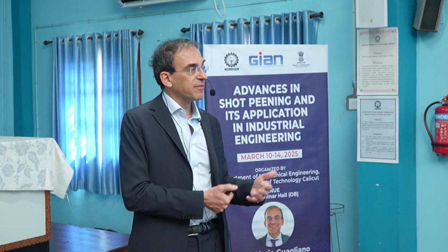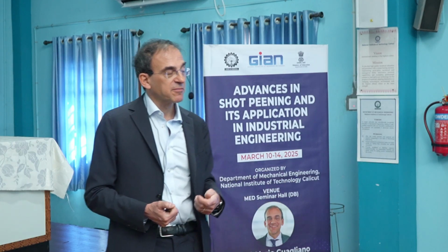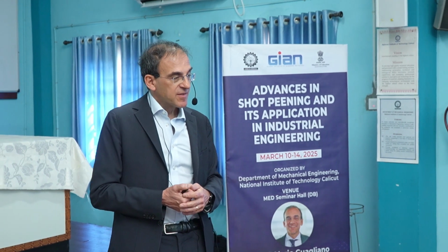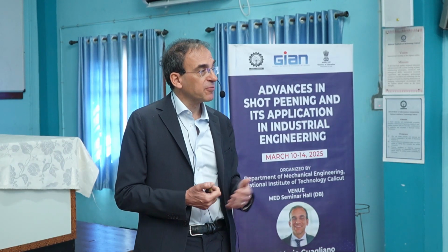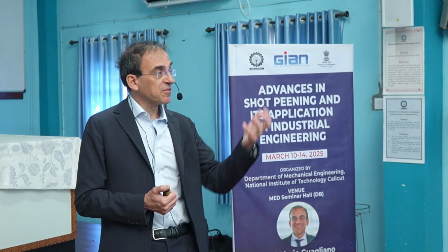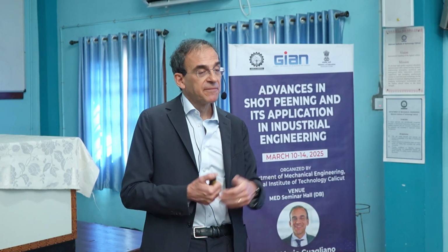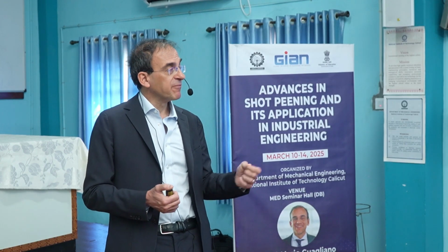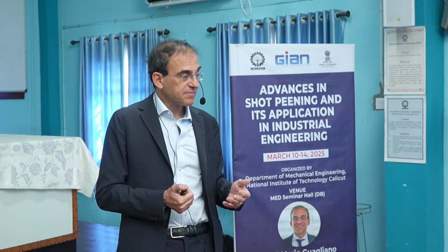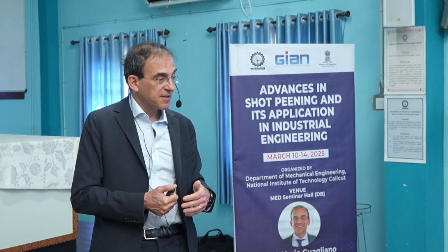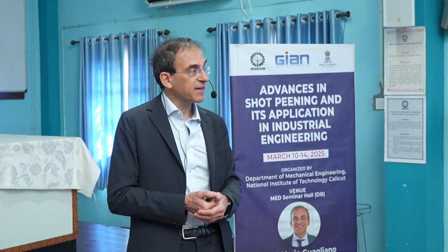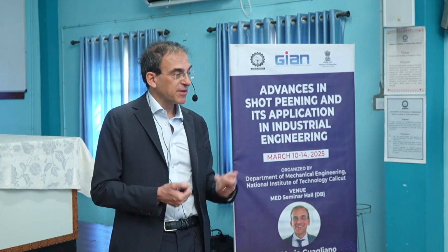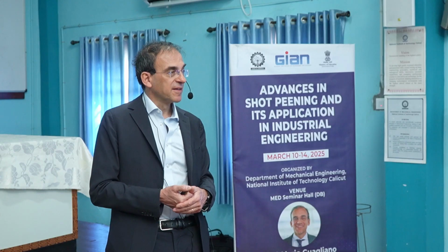Initially, in terms of macro residual stresses, and then also in terms of hardening, we will see, and in terms of surface finishing, surface roughness. So initially with the finite element model, with simplified approaches, one single shot or a limited number of shots, and then later also with other methods that are able to consider the shot flow, I mean the discrete element method, another method that makes possible an even finer understanding of the treatment. And what is going on? Indeed, the simulation and the other parts go on.